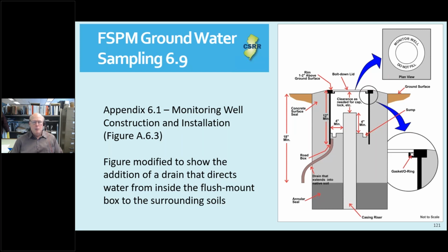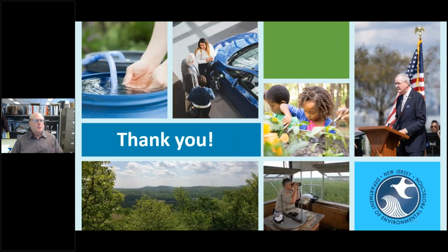Where relevant, DEP is looking for documentation of sample method, sample date, sample depth, sample temperature, sample turbidity, initial depth of water, well recharge rate, purge volume, variation in pump depth during purging, variation in water level drawdown during purging, and residency time of the sampling device in the well. This concludes my presentation. Thank you.